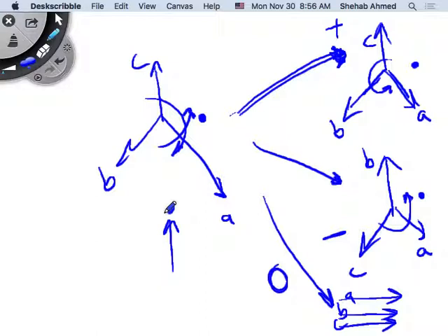If you flip the sequence of the supply, the rotating field will rotate in the other direction, and the motor will rotate in the other direction. Okay? But now, when you have an unbalanced supply, you're taking the field in one direction and putting, at the same time, another one. It's superposition, right? This is equivalent to these three together.